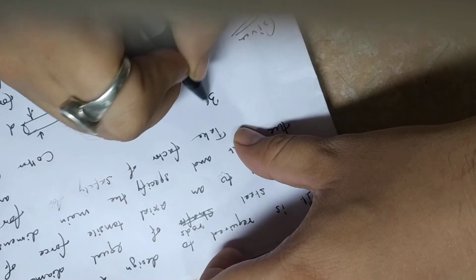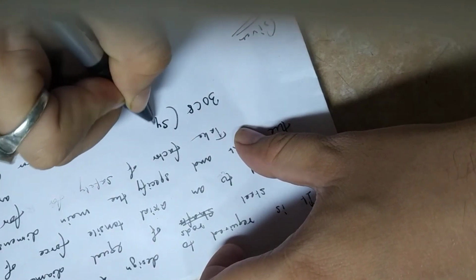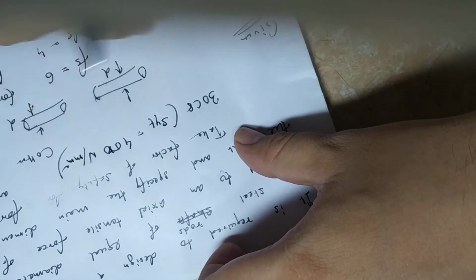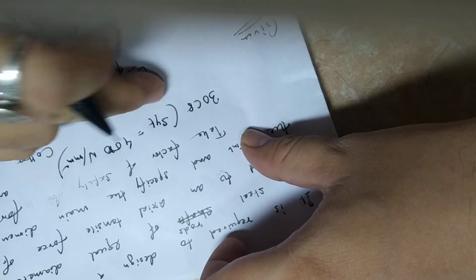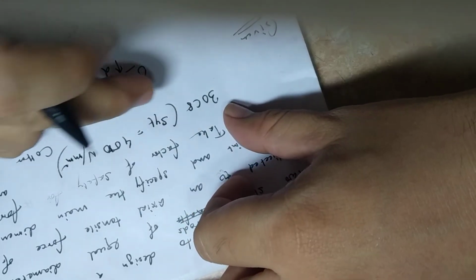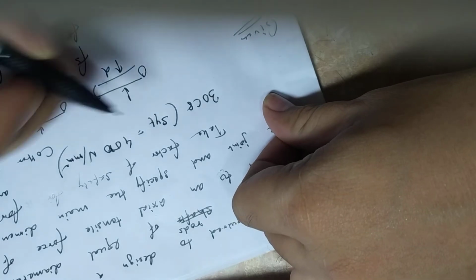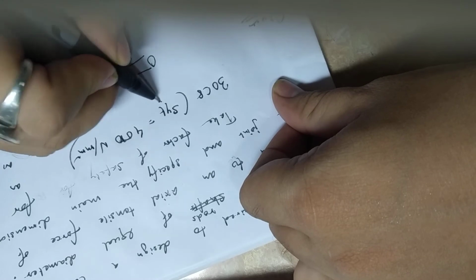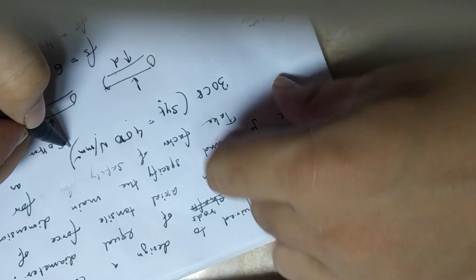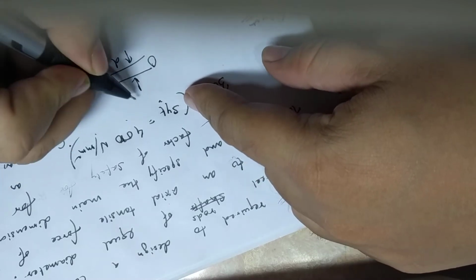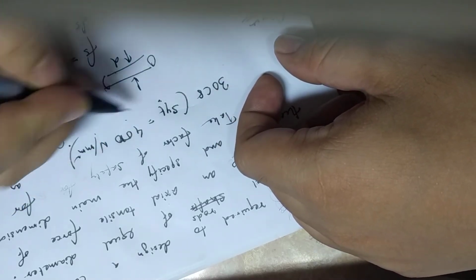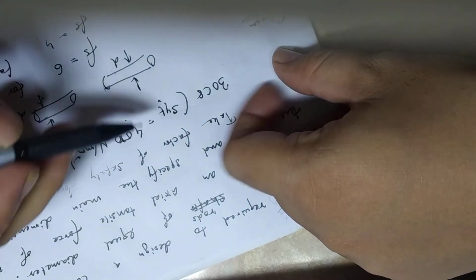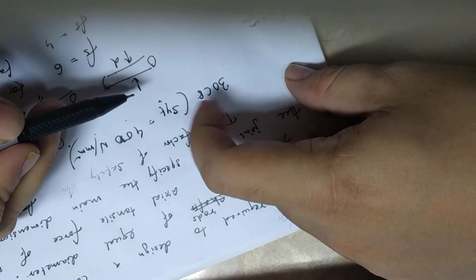From a numerical we'll take this value, so this is also given to you. 30C8 is a plain carbon steel, and its yield strength in tension is given as 400 Newton per millimeter square. There is no information about ultimate strength, so we have to solve the numerical to prevent permanent deformation. Yielding is the permanent deformation, right?